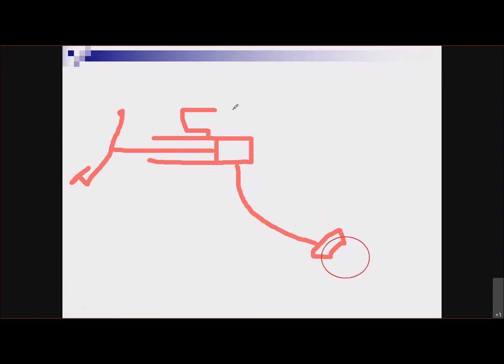So I'll put the reservoir up here, and it's got fluid in it, right? So when the piston moves far enough back to open this port, then fluid comes out of the reservoir and fills up any empty space in here. And then when the piston moves forward, of course, it blocks off that port so that fluid doesn't push back into the reservoir when you're stepping on the brakes.